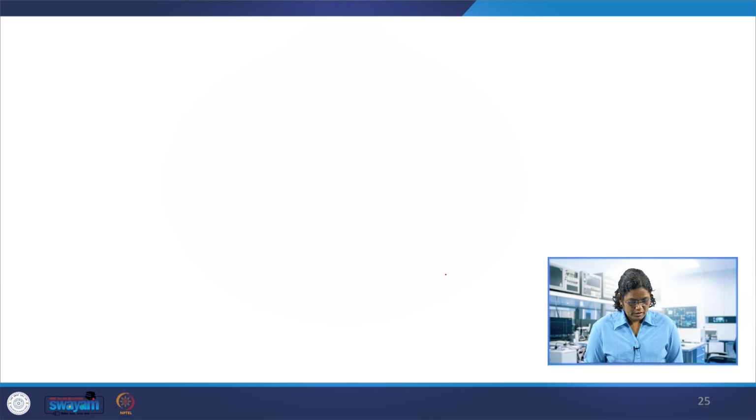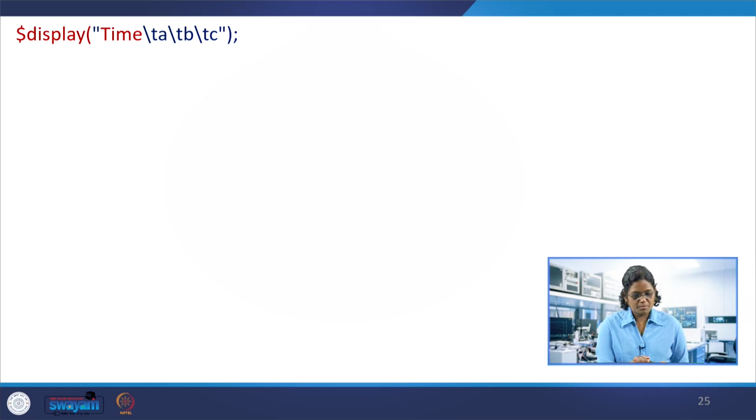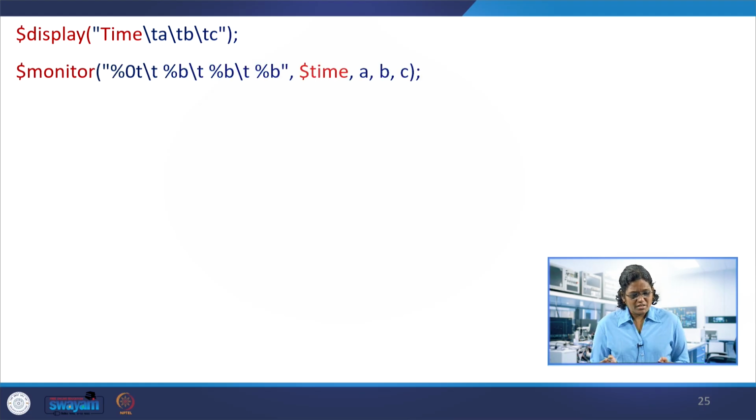Now the initial begin, the display shows ABC, and it is only displaying ABC, not the code. But in the waveform editor we can see it, because the output is declared in the module, so the output will automatically come in the waveform viewer. But when you want to print it in the console, you need to add the output also here. It's not added in this.